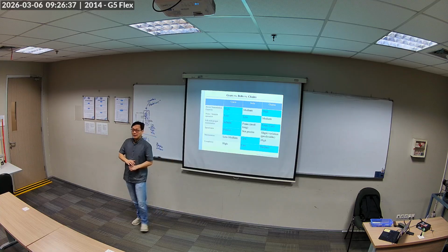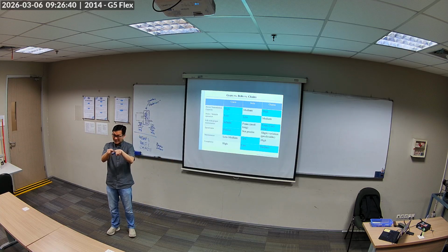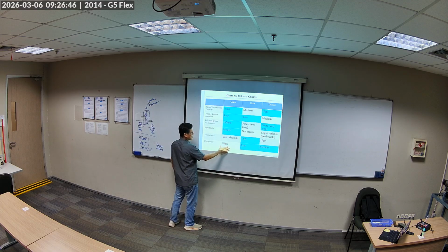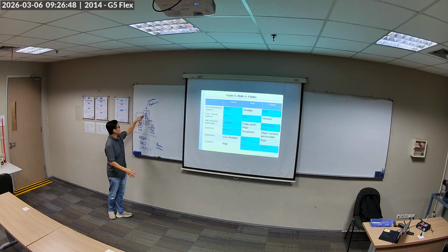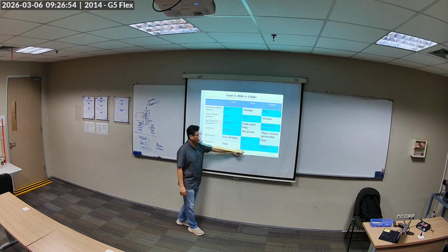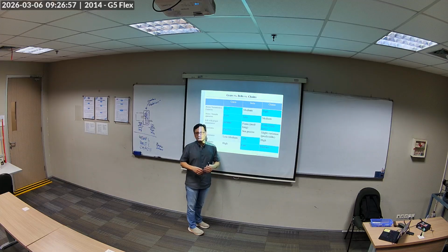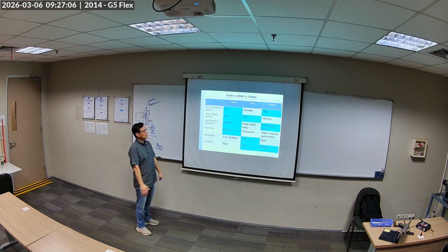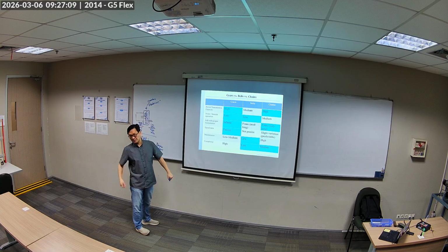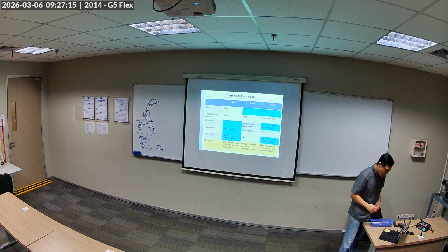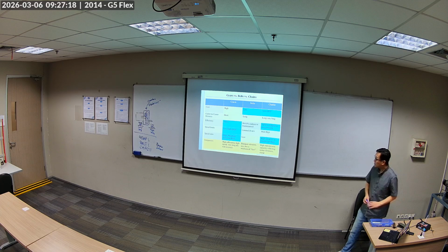Okay, complexity. Gears are highly complex. The distance between the centers has to be precise. The pitch radius has to match. The module has to match. So high complexity. The mounting of these axles on bearings, pretty complex. Belts, very low. Put the pulley in, set screws, put the belt in, adjust it a bit. Very flexible. Chain is medium complexity, just sprockets, put it on. It's relatively simple.